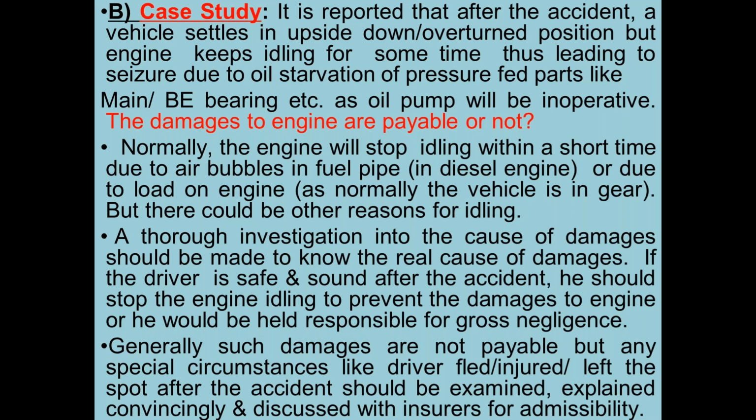Case study. It is reported that after accident, a vehicle settles in upside down or overturned position, but the engine keeps idling for some time, thus leading to seizure due to oil starvation of pressure-fed parts like main and big end bearing, etc., as the oil pump will be inoperative in that condition. Are the damages to engine payable or not?